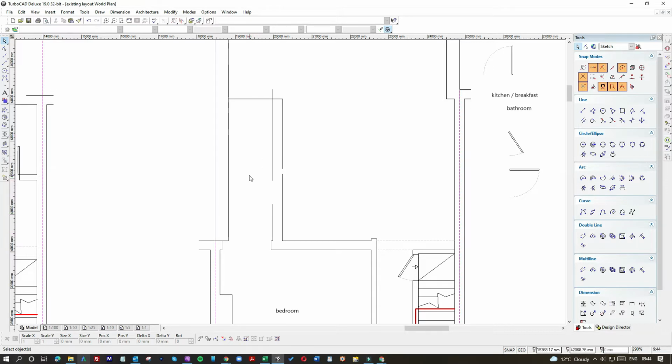And now, new building regs, with regard to light and space, mean that we don't build from this point forward in the sense that we used to do. We'd fill in all of the side and create a side extension, and you just walk into it here. But new building regs, which relate to getting light into this room, make a determination that we now need to leave a light well, and the light well needs to be, say, you could argue with it, but say 2 meters.